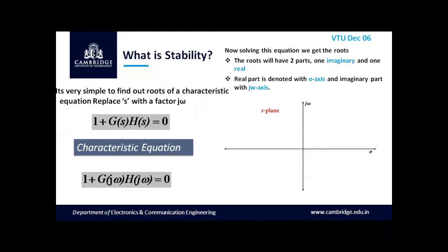And for stability related to the location of poles, one can say that a system is stable if the poles lie in the left half of the S-plane, and it is unstable if they lie in the right half of the S-plane, and it is called marginally stable if they lie on the imaginary axis. But how do we say that? The answer lies here with the question: what is the inverse Laplace transform of 1/(s-1) and 1/(s+1)? So let us take a few examples to justify the statement.